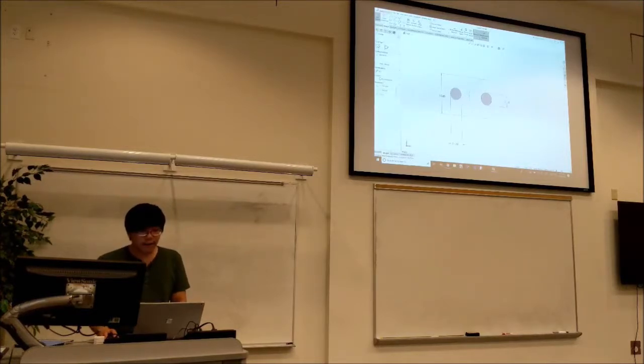And now this is the gear that's going to mesh with this gear, right? So we can set the center distances two different ways. One using just a line and then dimensioning the line. But because we modeled these gears as the pitch circles, we can actually just make the two circles tangent. So now it kind of looks like a gear, right? This gear is just rotating and it's going to rotate this output gear.